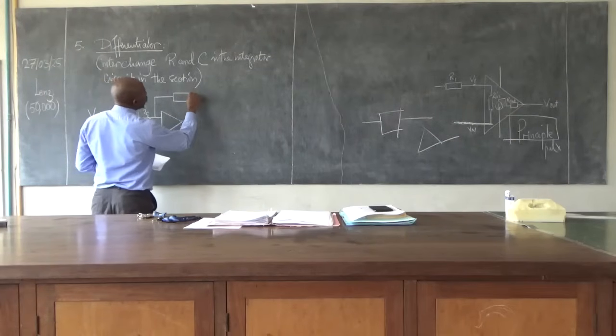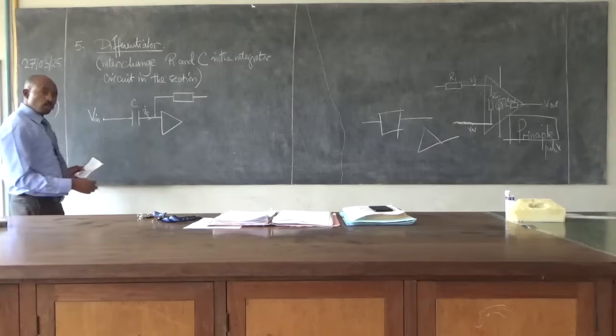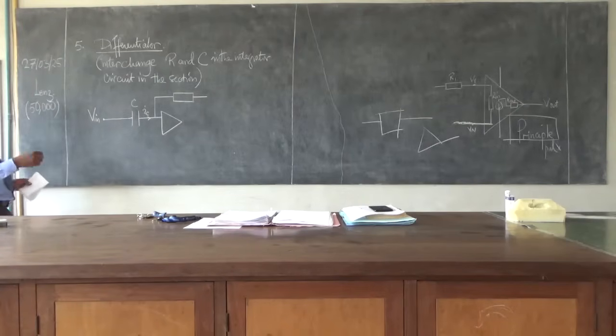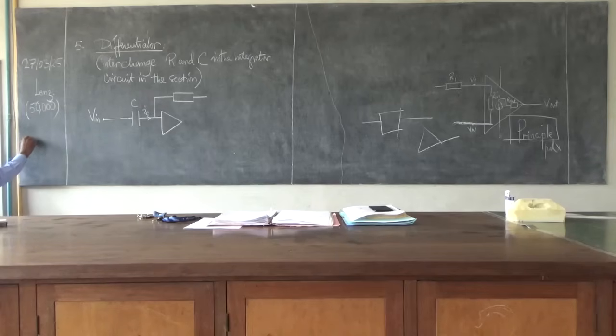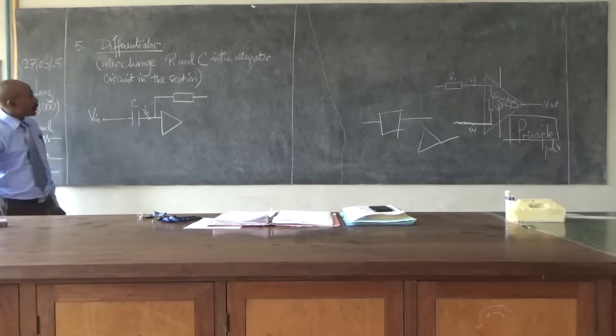A resistor is a rectangle, and if you are sure that this resistor was formed from a coil, then you make this. This is fixed, and if it is variable, then you put an arrow through. If you choose to make it a rectangle, which could be any material that gave resistance, and if it is variable, then you draw a strike through. That's how the resistances are put.